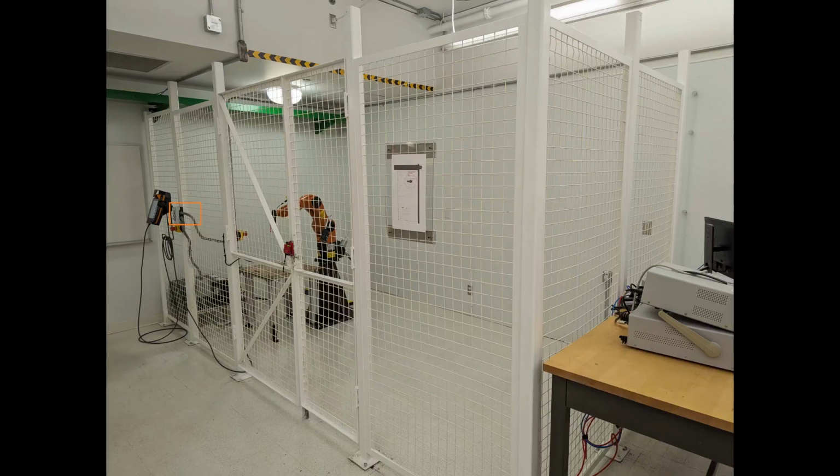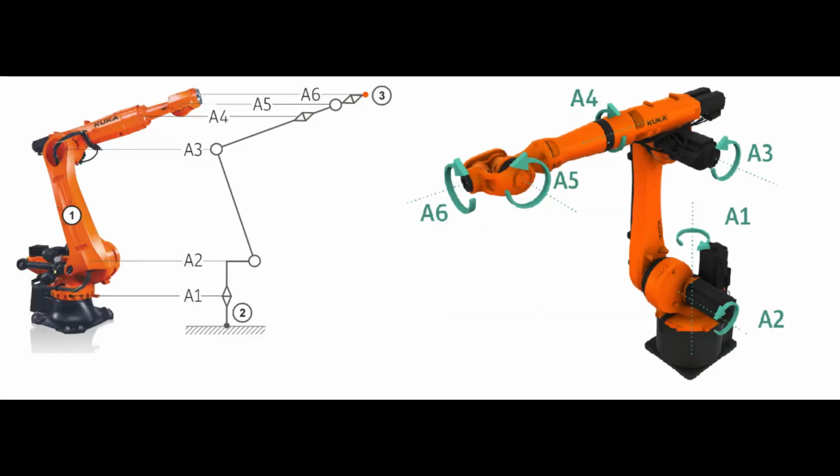An external I/O card to add additional control inputs and status indicators to the robot system. The arm consists of 6 motors and is able to position an object at any point in space along the X, Y, or Z axis with the desired orientation profile about the X, Y, and Z axis within its workspace limits.